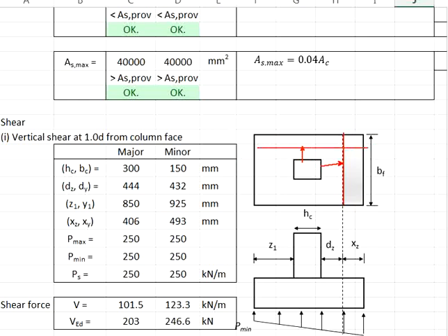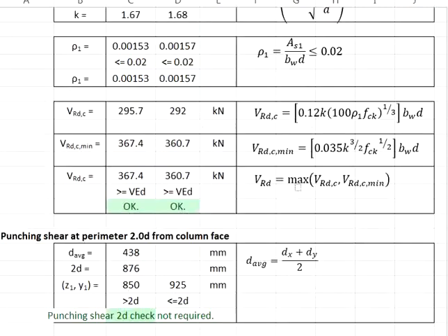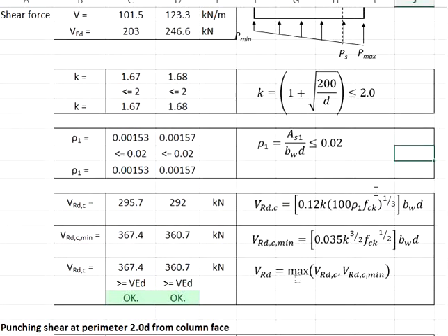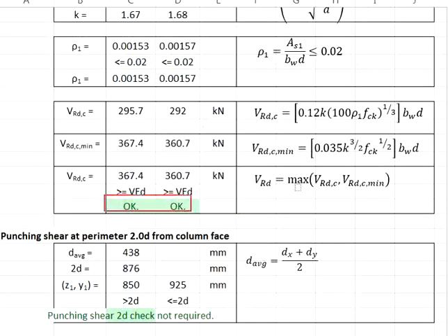We have two shear planes to be checked, 200 and 240 something. You see now your shear resistance of the pad footing is greater than the shear loads calculated. Therefore, your shear resistance is adequate.